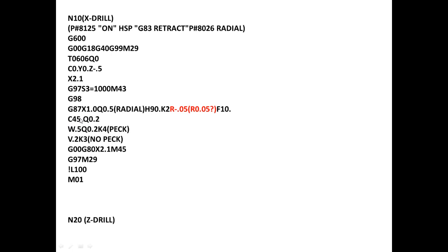Jinho, we have a question here. It says, can we go over what needs to happen when locating sub-spindle C values after parting off, if it is never right when it's set up without changing C values on the sub-spindle? It sounds more like a part transfer question. Yeah, phasing, Jinho. So spindle phasing at cutoff. So part transfer, spindle phasing is basically the question.